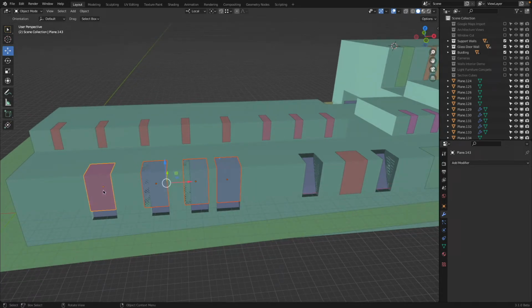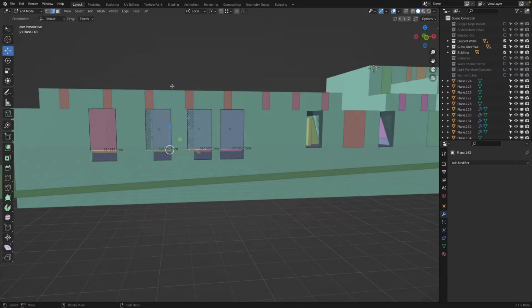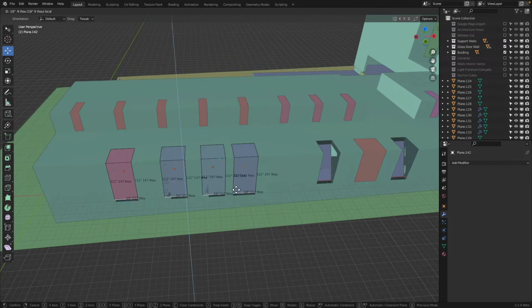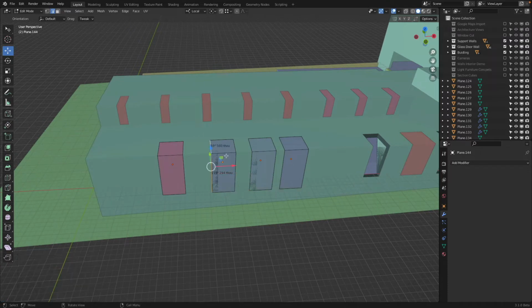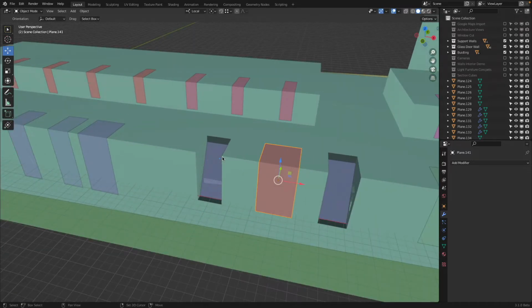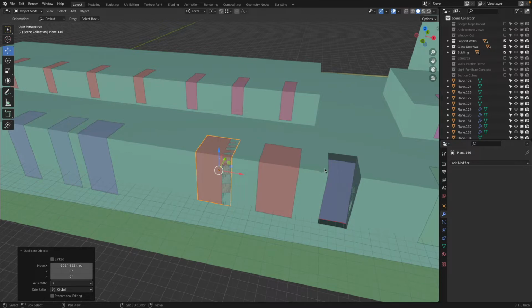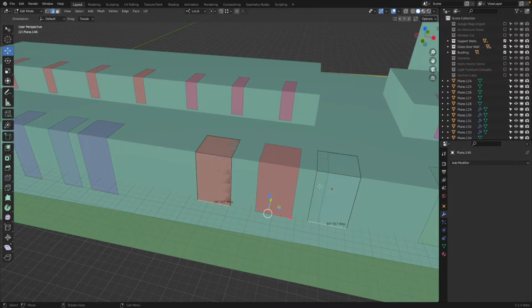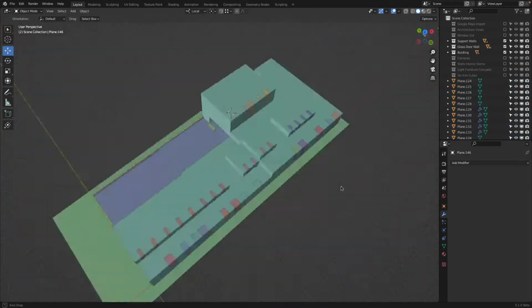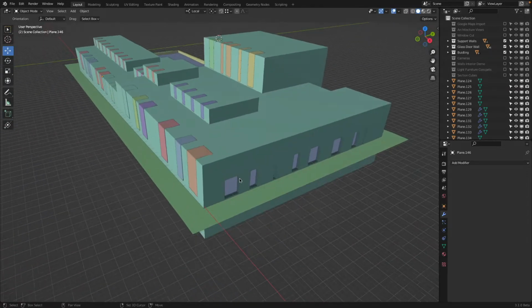What's really nice in Blender is you can select multiple objects, and then when you go into edit mode, you can select multiple geometries at the same time. So you don't have to go into edit mode, leave edit mode. It would be great if SketchUp could do this more. Shift D, go to there, Shift D, go to there, edit mode for both, and there I'm with Control snap, finish this. Yeah, there we have this super easy.